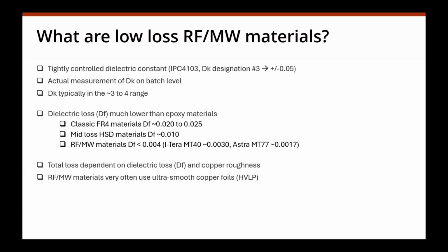Amit has just listed 0.005. I'm not going to really put a hard limit down here. The main message here really is you're talking about a quarter or less of the Df that you would see on standard FR4 materials.